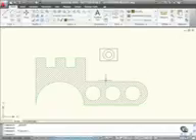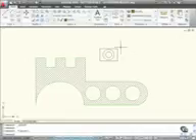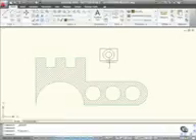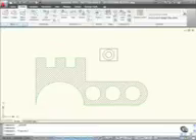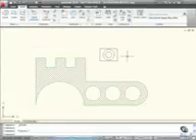What we'll also do, we'll make a block of this group of objects here shortly as well. So let's create a block of our widget first, and then this is our casing. So we're going to create a block here. Now, to create a block, you've got the block panel here on the Home tab, and there's Create right there. You've also got on the Insert tab a block panel, where you can insert, create, and also go into the block editor to start looking at dynamic blocks.